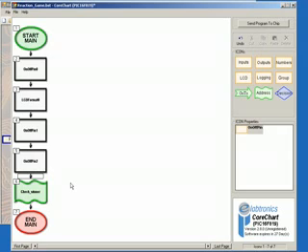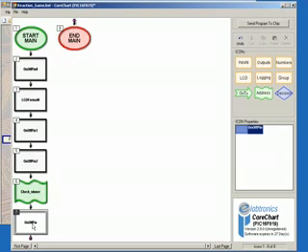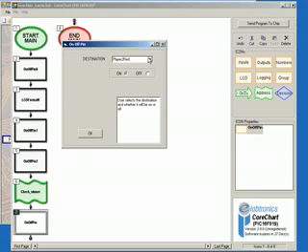We'll now select outputs yet again, followed by on-off pin, and place it by clicking the black arrow below icon 6. Double click on the icon to bring up its options, and select D7 yellow LED as the destination, and off, and then click OK.